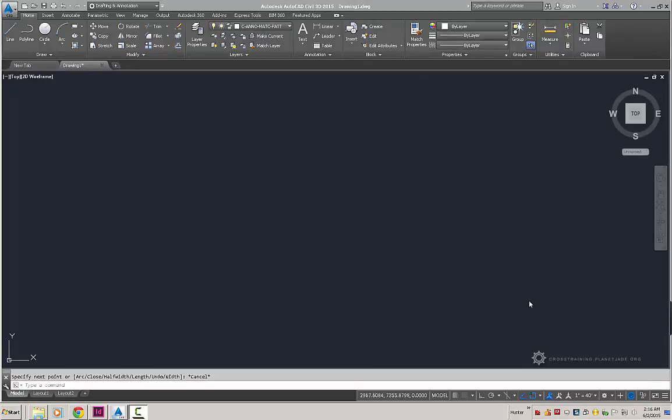So in our example, we want to draw a line that is 150 feet long, that is running north 60 degrees, 30 minutes, and 0 seconds east. So the next step is we need to determine which one of our coordinate systems we wish to use. Our options are absolute polar, relative polar, and absolute. Obviously we're not going to use absolute because we need to know the exact XY values of each of the points, and we don't have that information because we're starting from some point somewhere in space.